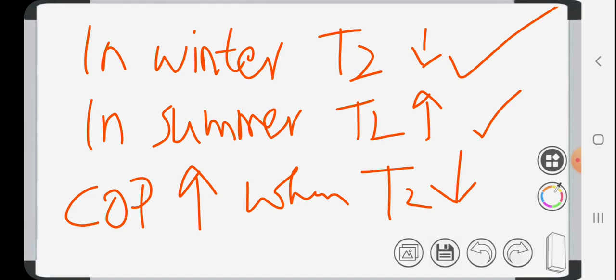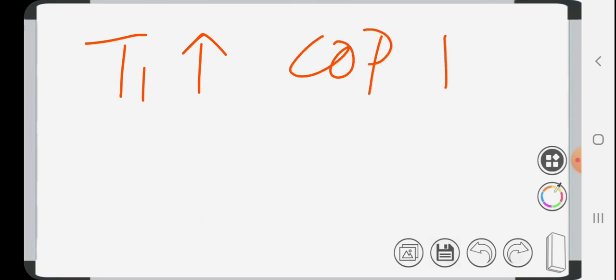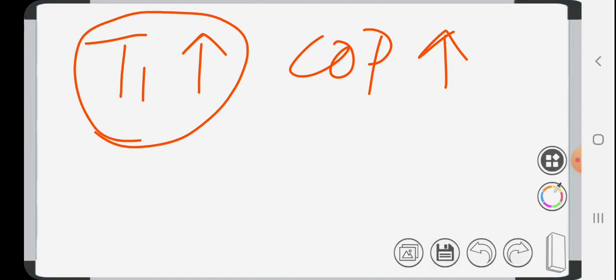Also, if the lower temperature T1 increases, COP increases. That is, if the lower temperature is high, the COP of the Carnot refrigerator will be high. The lower the refrigeration temperature required and the higher the temperature of heat rejection to the surroundings, the larger is the power consumption of the refrigerating machine. So students, increasing the temperature of the space to be cooled is not acceptable, right?